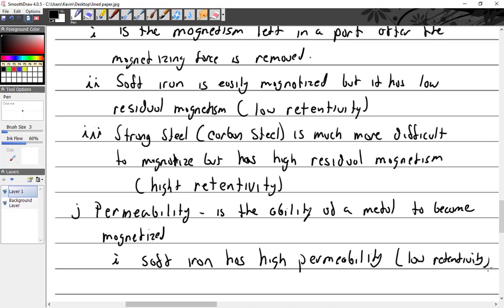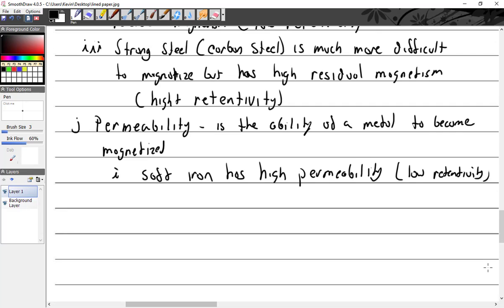Goes away. So if I want to talk about this in terms of non-destructive testing, which may or may not make much sense to you, I don't need a lot of amperage to magnetize something that is soft iron, and I can easily work with it within the machine on lower amp settings, but the minute I remove the current, I've lost the magnetism of it, or very little is left. And we can turn that around and say the opposite.